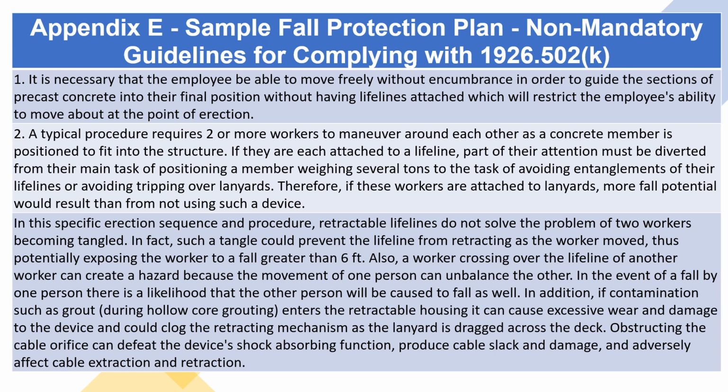Also, a worker crossing over the lifeline of another worker can create a hazard because the movement of one person can unbalance the other. In the event of a fall by one person, there is a likelihood that the other person will be caused to fall as well.